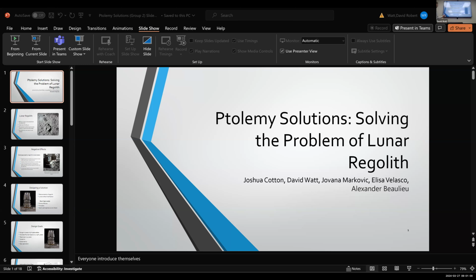However, we chose to layer it with 3 layers of Cryogel Z insulation, which is about 15 millimeters thick, and that reduces it significantly all the way down to 474 watts. And with that amount of wattage going into the chamber, the internal temperature heats up to only 5.9 Kelvin, which keeps the pressure near the target range of 2 kilopascals.